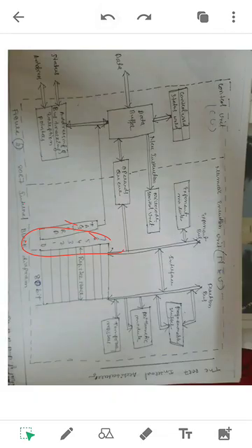So refer to this figure. Let us see what is the control word. The control word of the 8087 is written to a memory location, and the 8087 executes an instruction which reads the control word from memory. To read the status word from the 8087, we require an instruction which writes the status word to memory. Here you can see we have the stack.